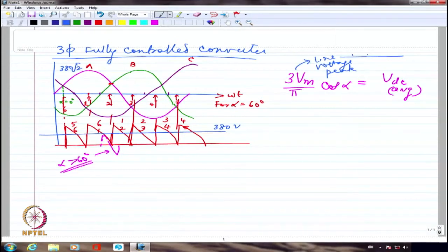So if I have something like this, obviously the resistance will conduct only for this duration. Why would it conduct for any other duration? The devices will be forward biased only when the battery voltage is subdued as compared to the voltage that is coming up across the DC link. Otherwise, the devices are not going to conduct, right? And we are assuming ideal devices, of course. So if at all you have to put down the assumption, you should say ideal devices. That's all. Okay? Anyway, we have done all the analysis using ideal devices.